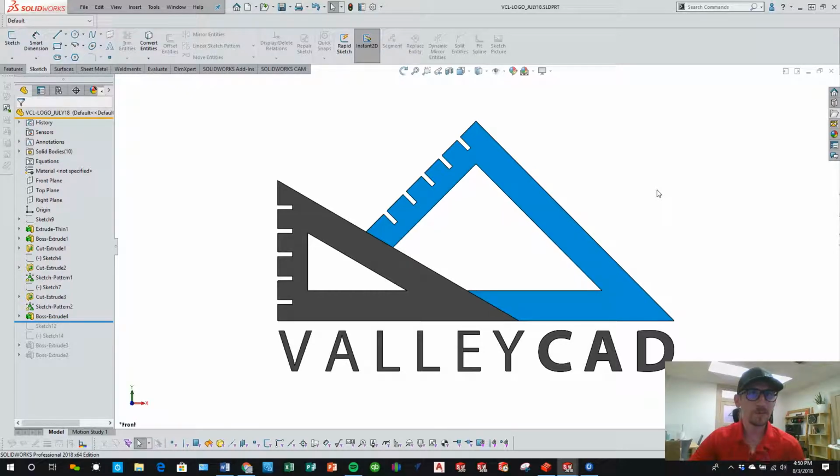So I keep talking about this thing called SOLIDWORKS Rx, and utilizing SOLIDWORKS Rx is extremely easy. It's a software that SOLIDWORKS automatically installs when you install SOLIDWORKS. It's that awesome. So looking at simply your SOLIDWORKS user interface here, you say, all right, I want to access SOLIDWORKS Rx. Where do I go? Well, you would actually come over and select your SOLIDWORKS Resources. That's that little home icon in the right corner. Remember, this is called your task pane.